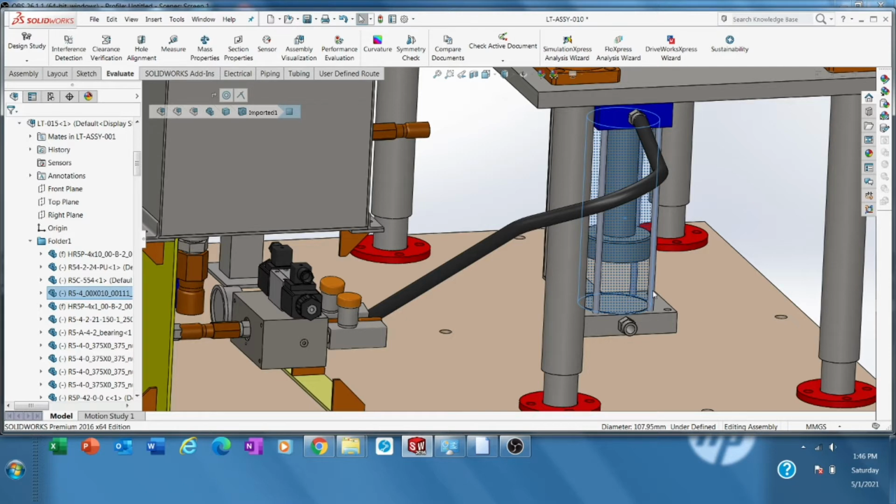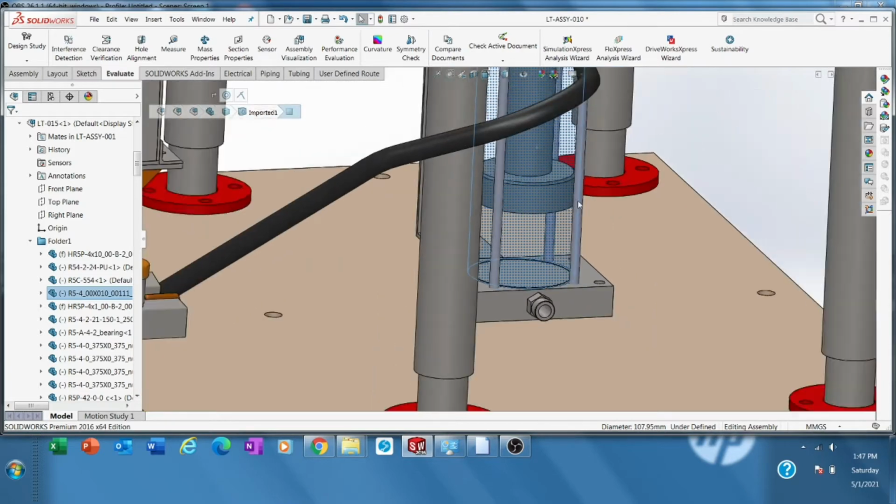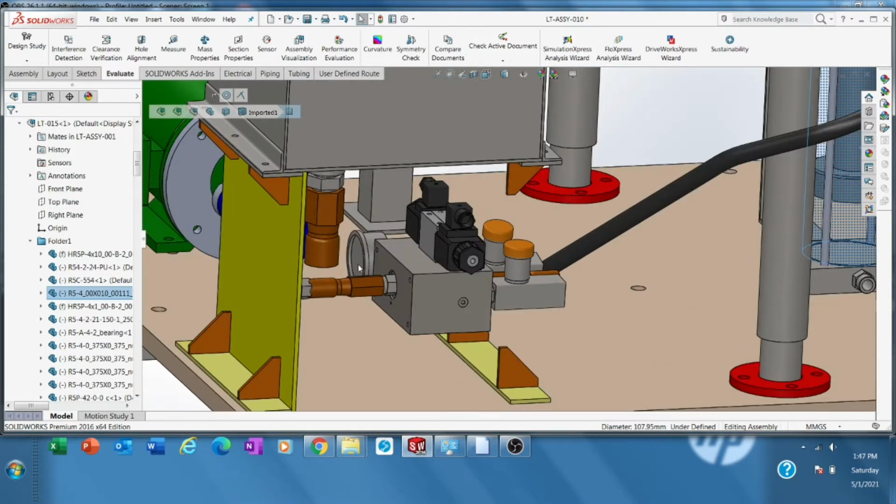For example, if you have a flow capacity of 23 liters per minute, as previously said, and you want to maintain the capacity for 3 minutes with no shortage, you need at least 3 times plus all the volume inside this. So let's say 70 liters or 50 liters, that's the basic one. Someone may design only 2 times or 1.5 times, but to avoid the fluid getting very hot, usually 3 times.